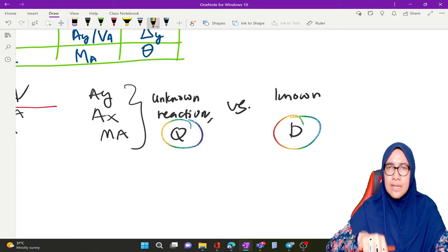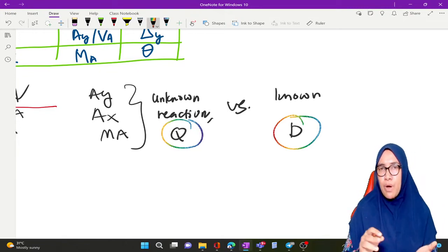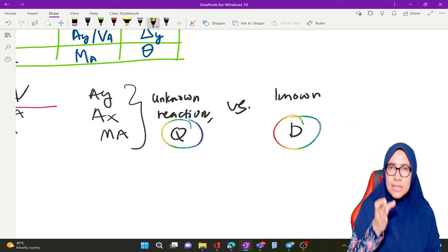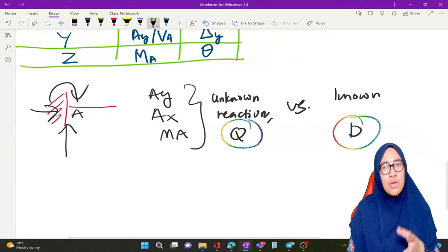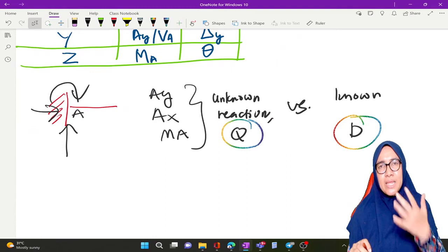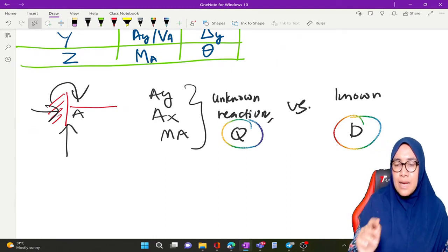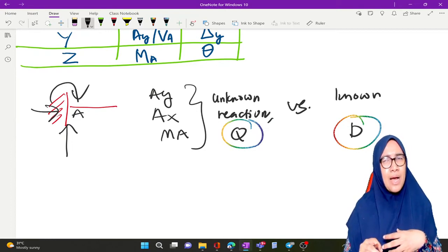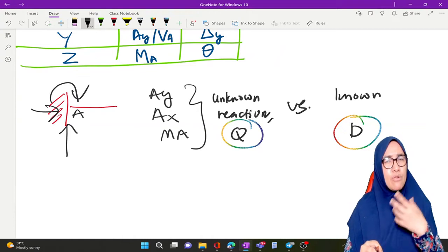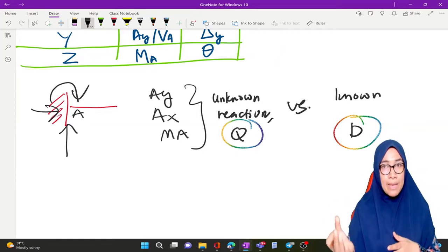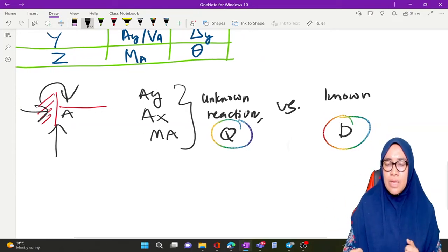Displacement at these three components at fixed support equal 0. Displacement due to fixed support equals 0. That is why when we draw, for example, deflection in a cantilever beam, this is how we understand the concept of degree of freedom. We try to understand it for all beam, frame, and truss as well.